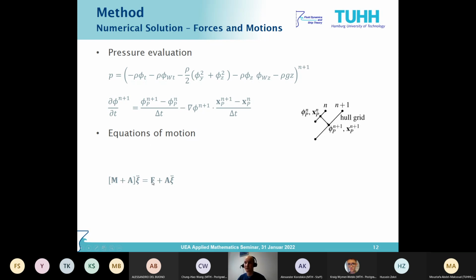Now, this force does not contain the acceleration dependent part, but the acceleration dependent part is written like this, and also put on the other side. And this is also why it's called added mass. There's this coefficient. And this is just to make the simulation more stable. Then we can calculate the acceleration, and from the acceleration we can calculate the position by integration.